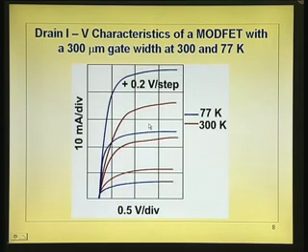So, two temperatures are given. I would like you to observe this characteristic carefully. There are two things to observe. One, the spacing between the curves is more. See, for 0.2 volts the spacing is almost 2 divisions, that is about 20 milliamperes. Whereas if you take these two curves for the same voltage difference of 0.2 volts, it is slightly more than 1 division. So, it is not double the current, but almost double.